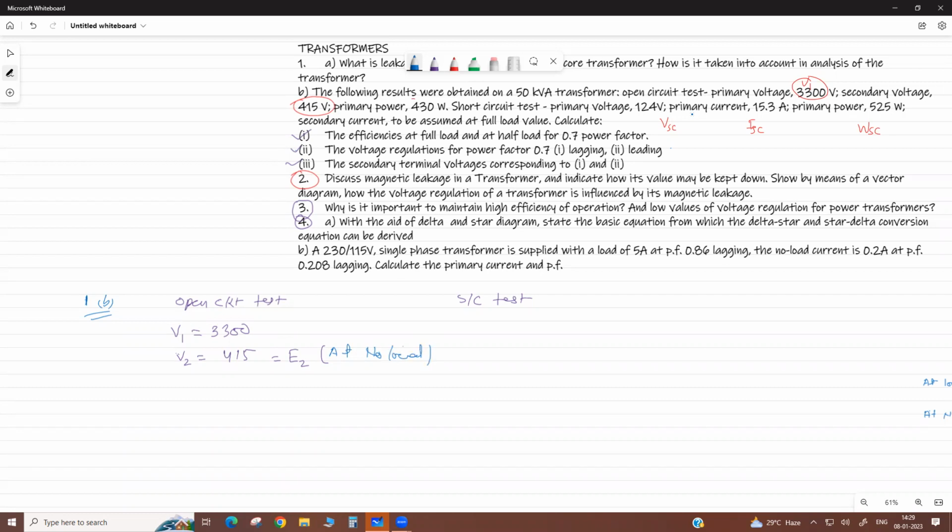Then you write. Now when we apply at no load, there is a power input. So this no load input power W0 will give the iron losses equals core loss. Please remember, that is generally V1 I0 cos phi 0, means no load input power.